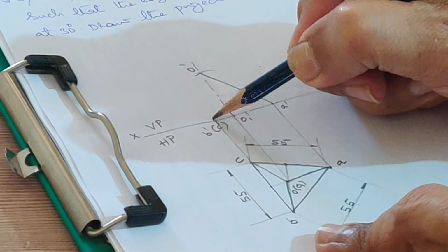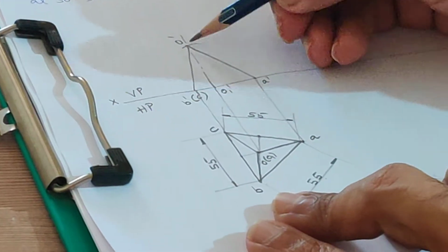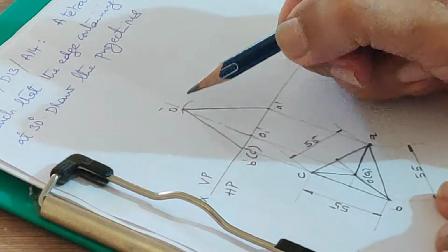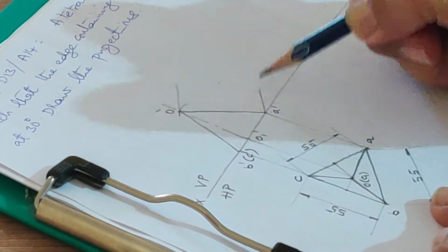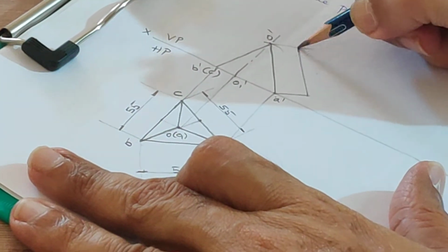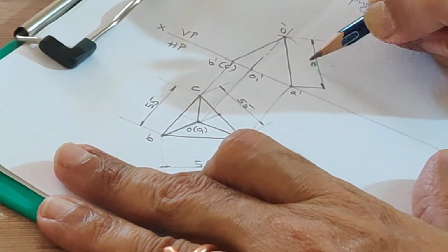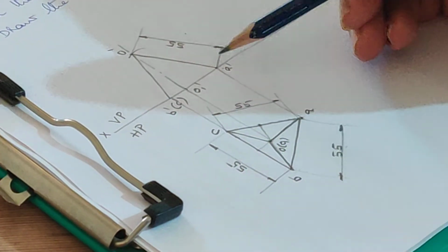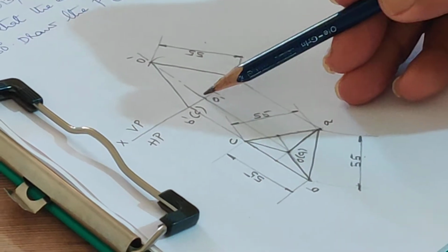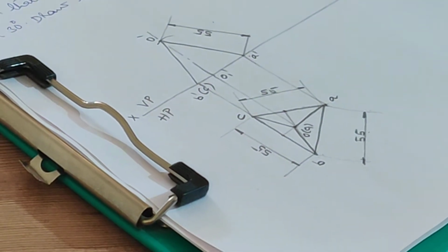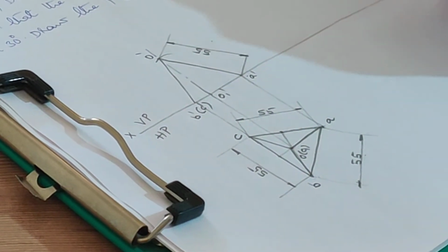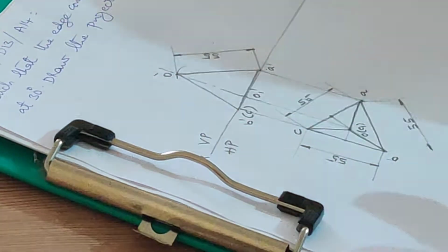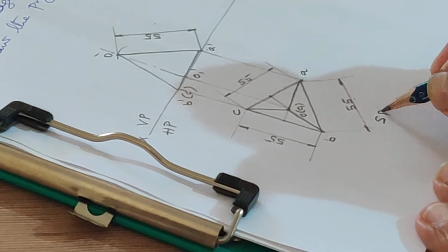Now you can complete the front view. So only OA is in its true length, OB and OC are in their apparent length. You can mark the dimension for this as well. This has to be 55. So we don't know what the height is, that's not important for us. But this has to be 55. This height could be any dimension. We need not dimension it. Done. This is the front view. Of course the base has to be dark. Yes. So this is SP2.